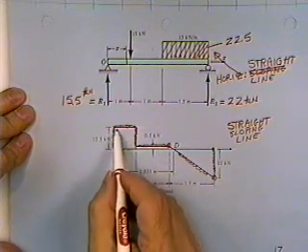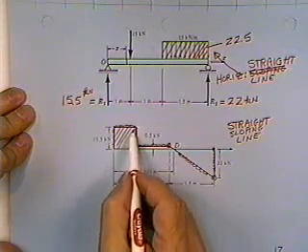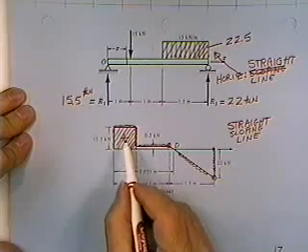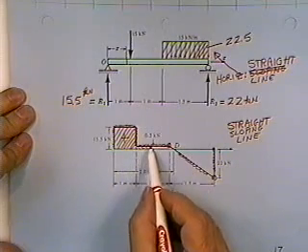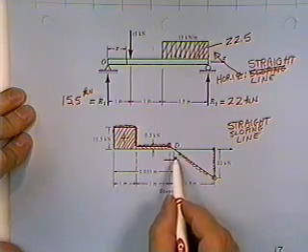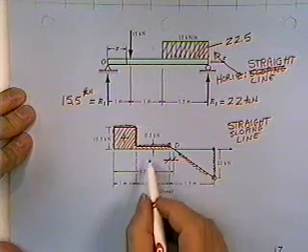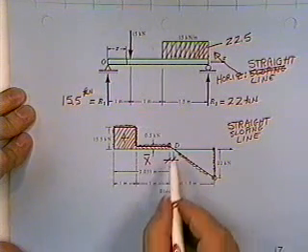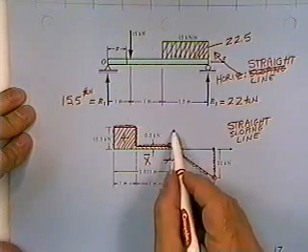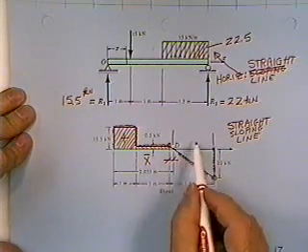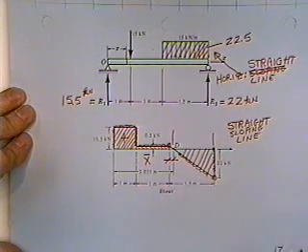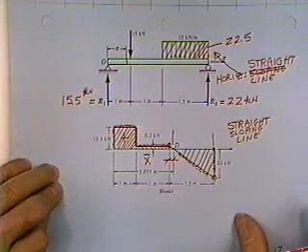The next task we have will be computing this area, which will push the curve up. Computing this little x-bar distance right here. So we know how much area is underneath this little tiny triangle, and so we will know the base of this great big triangle. And knowing that base, we'll compute the area of a triangle, and that'll be used to calculate the moment diagram.